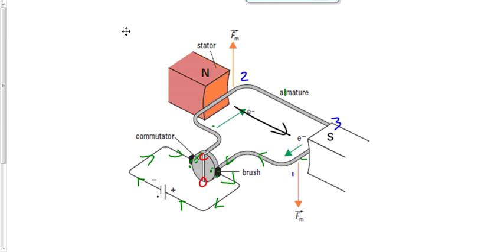That doesn't mean the armature stops, though. The armature has inertia. There's linear inertia that we always talk about, but there's also rotational inertia. If an object is spinning, it wants to keep spinning. So it does a little bit. Wire 1, 2 is forced upward, 3, 4 is forced downward, 90 degrees. The force stops, but it will keep spinning a little bit because of inertia.